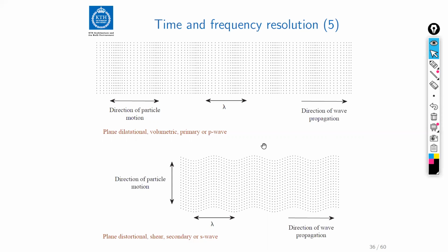Now, these types of waves only occur when we look at solids really. So in beams and common structural systems that we look at for bridges, we typically don't consider these waves, because these waves would propagate in the actual structural materials, that is, in concrete or steel. But these materials are so stiff that these waves have frequencies that are way outside our scope of interest.